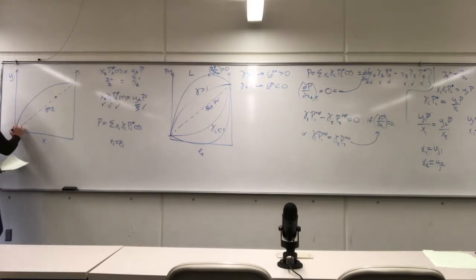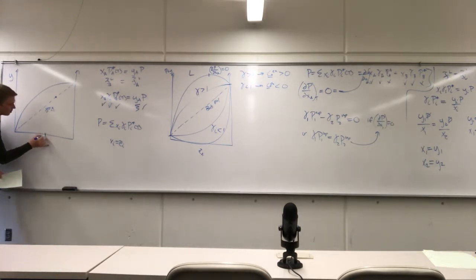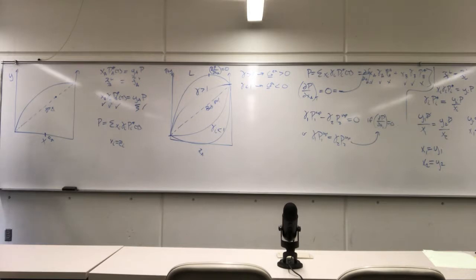Now what happens then is that normally, so let's think about this, we typically draw all of our diagrams based on the more volatile species. So if I choose some arbitrary composition here, let's say a 50% liquid mixture, the vapor phase is going to be higher than 50%, because x is the more volatile species. And that's a nice convenient way so that all these diagrams look the same. So every time we look up a diagram, it's not a 100% new scenario. So if I choose a starting point right here, where I have a liquid composition of 50%, should my vapor be higher or lower than 50%? Because it's the more volatile species, it's going to be higher. The more volatile species wants to get away.